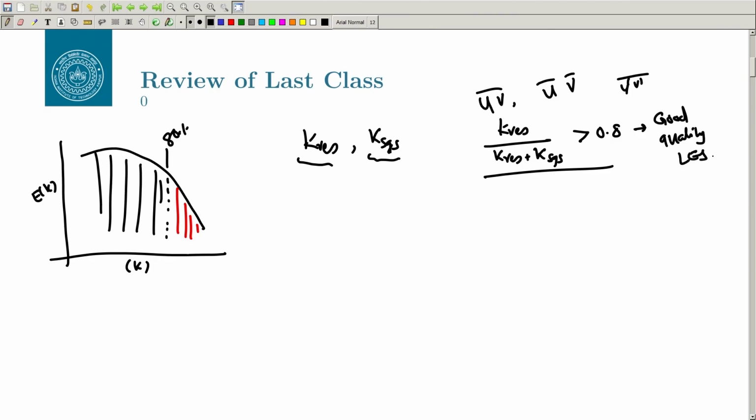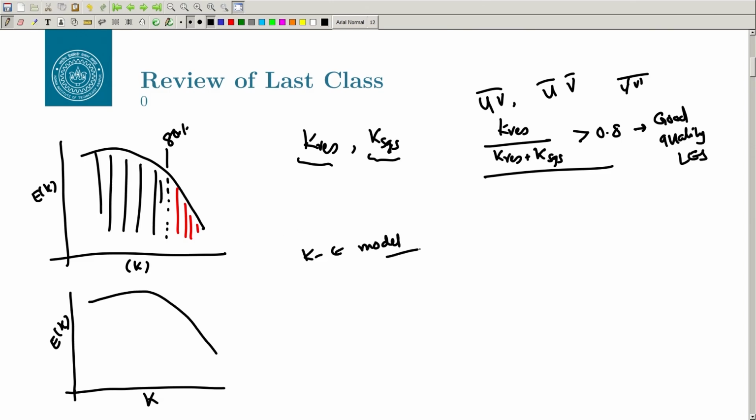So, this you can check once you have already performed the LES. The other thing we discussed regarding LES is how you decide the grid size before starting LES. Typically, you perform a RANS simulation, and from the RANS simulation, depending on what model you are using, let us say you use the k-epsilon model, you can calculate the length scale from this k-epsilon model.